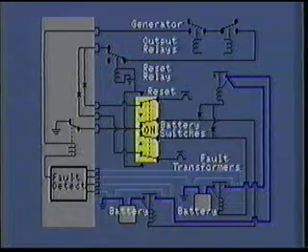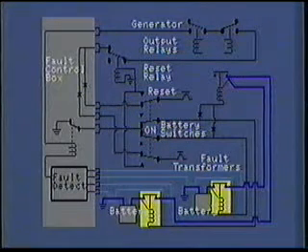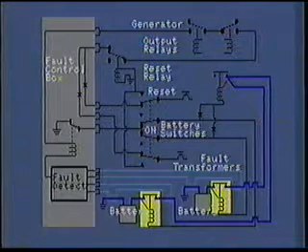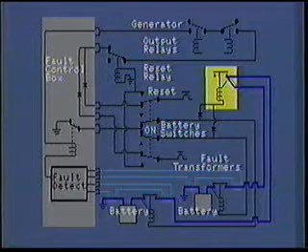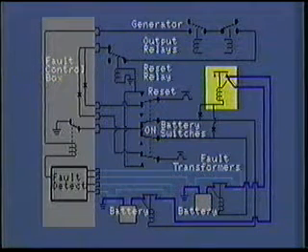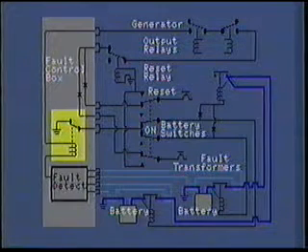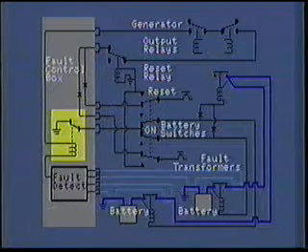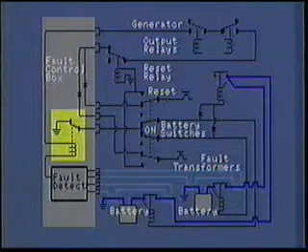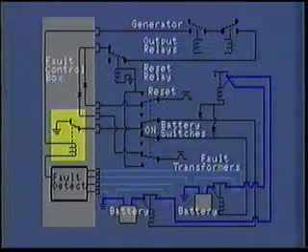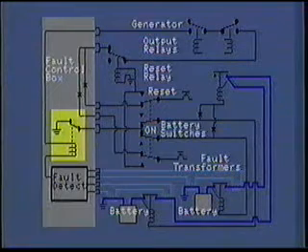The battery control system sequence is as follows. The pilot moves the battery switches to the on position. Then the battery relay closes, connecting the battery to the aircraft's electrical system. Then the battery bus relay closes, connecting batteries to the bus system. At this point in time, the battery fault system is not active, so the relay within the fault control box is relaxed. This is due to the fact that both generator systems have not been activated, a prerequisite to arm the fault detection circuit. After the fault system has been activated, an indication of a battery wiring malfunction will cause the fault system to trip and disconnect the batteries.